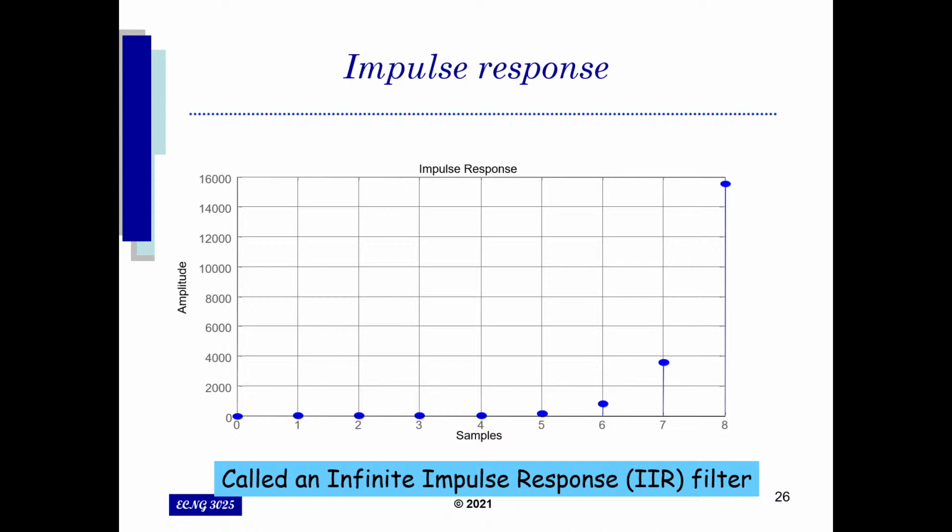When you plot the impulse response graph, you'll have to use some sort of simulation software to plot this for you. If you're manually plotting them, remember you're going to have to substitute z equal to e to the power of j capital omega, where the x-axis is going to be omega, and the y-axis is going to be the amplitude or the phase accordingly. There's an associated command in MATLAB that allows you to do this for Z transform equations, but I'm going to have to research this to make sure what the associated command is for getting you the impulse response graphs in particular. But we won't ask you to manually plot these graphs.